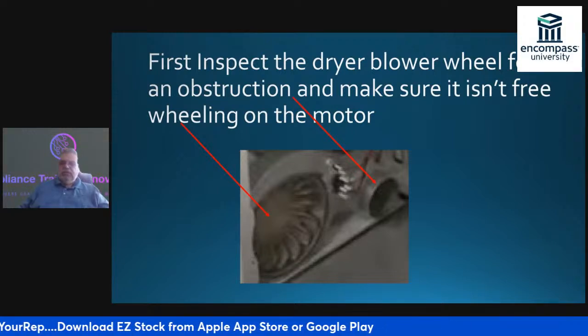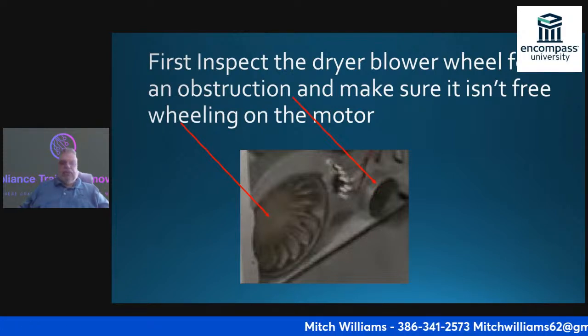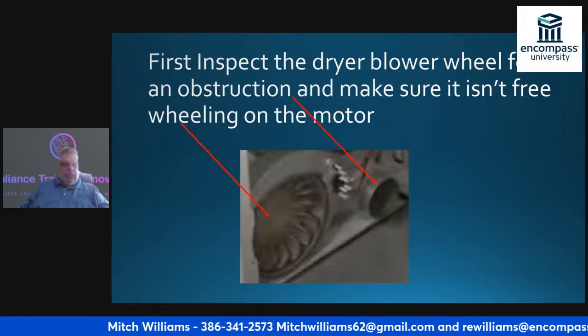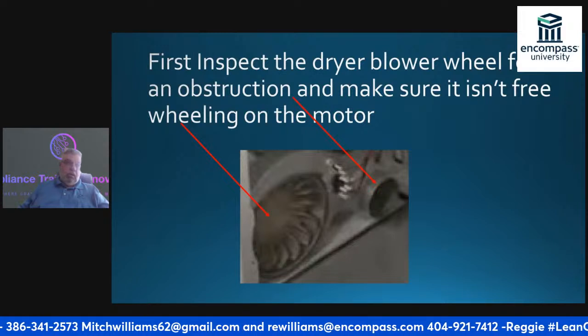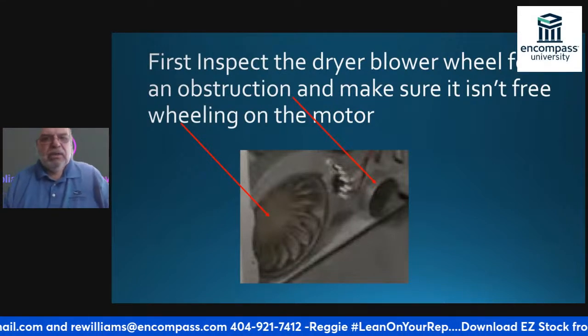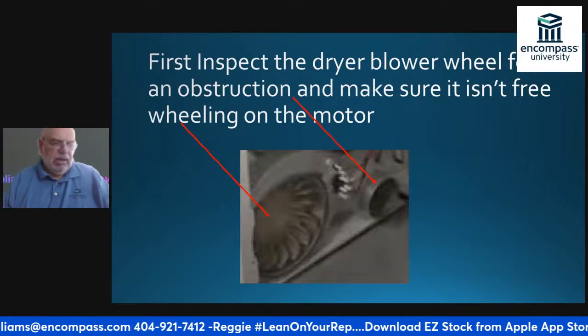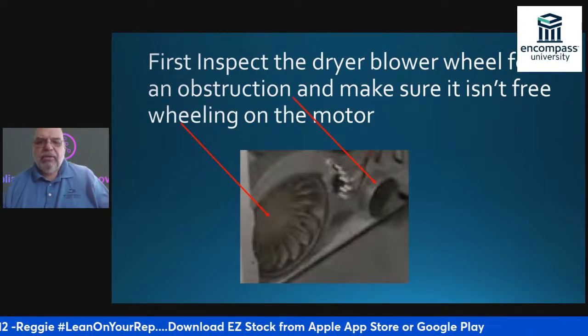That gets into something that's expensive. I have had one that I could not get off to save my life. I actually took that motor to the shop, stood the motor up, and put it in some penetrating oil overnight to be able to break it free. So most of the time, that is not something that you want to have to deal with.